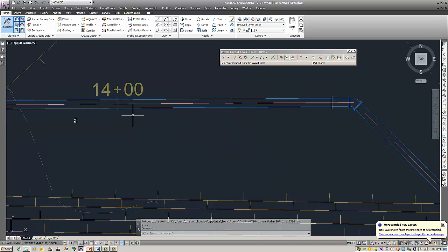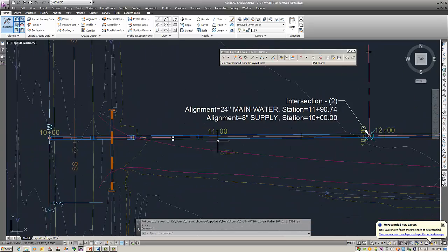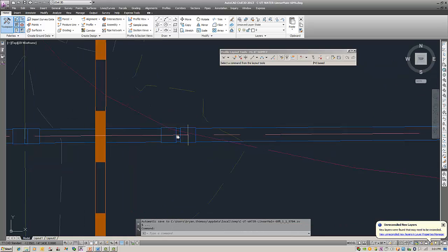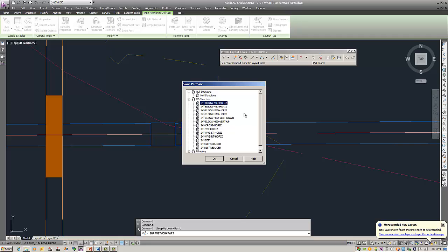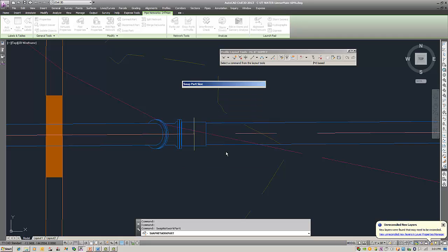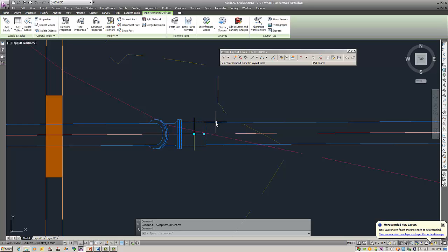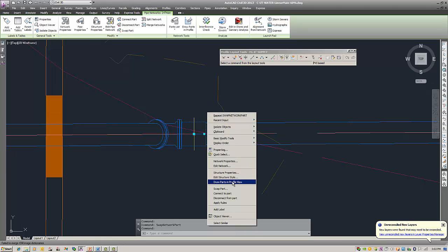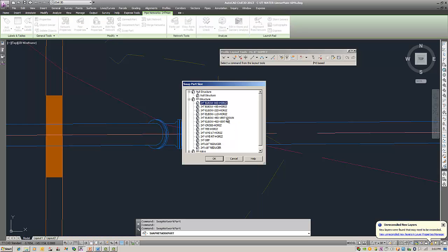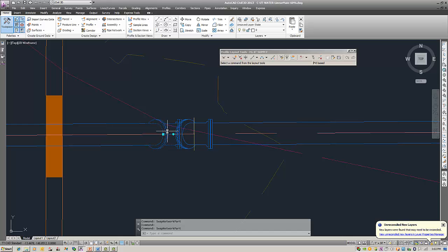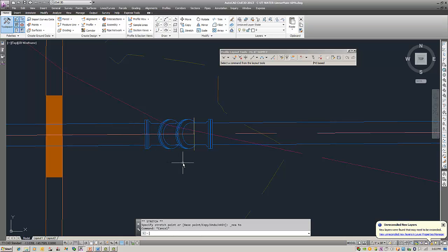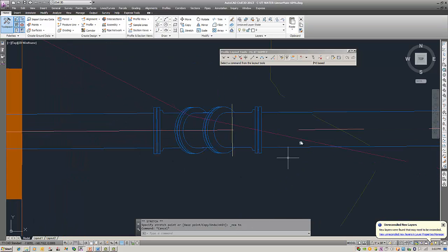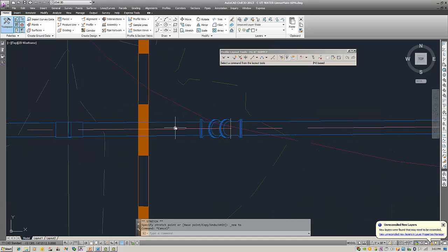So what you will simply now do is just go through and do a lot of swapping. You're going to come in over here. We know that these are vertical bends up and down, so I'm going to start swapping these parts out such that this is basically a vertical bend 45-degree up, and this guy I believe is a 45-degree bend vertical down. And when we rotate them through properly, you can actually start getting a feel of the 3D effect on it, that it's in fact coming along and then it turns and comes back up over.